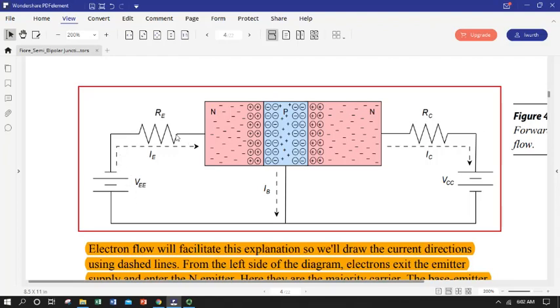Electrons are going to flow through our limiting resistor, so we don't get too many going at once. And electrons are negatively charged. They're going to hit the heavily N-doped material of the emitter. And you can think of those electrons as kind of repelling, like repels like, in terms of electrostatics. So the majority charge carriers in the N material, there's plenty of them, lots of mobility. They're going to go scooting across the emitter very easily, very few ohmic losses, and they're going to hit this